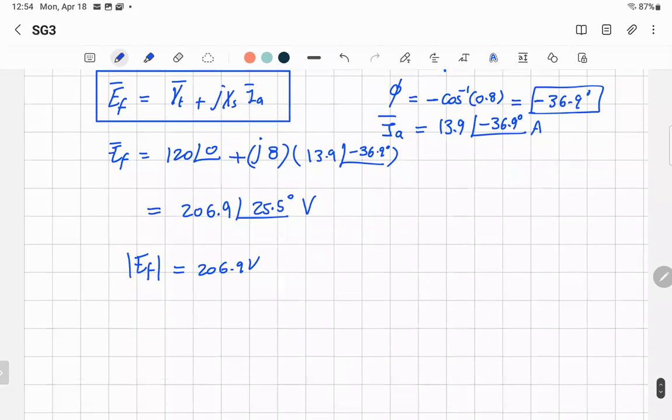Find the torque angle or power angle. So the power angle, it's delta, it's 25.5. It's also important to know how to extract the information here. How do you do the phasor diagram? We did that last lecture, but let me do it again. That's the terminal voltage; we always assume it's the reference. So that's VT, equal to 120 volts at angle 0.